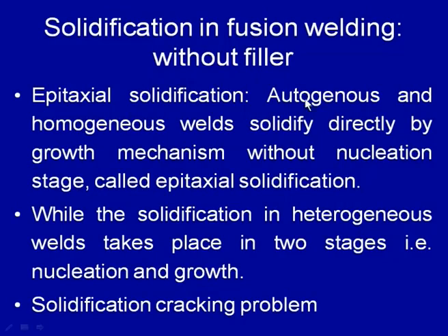Solidification cracking is called so because it occurs just at the terminal stage of the solidification or just after the completion of the solidification, as soon as high residual stresses set in along the weld center line and lead to the cracking. So, to overcome this problem of solidification cracking, various methodologies are used to change the grain morphologies even in the autogenous and homogeneous welds, if the change in composition of the base material is not possible.